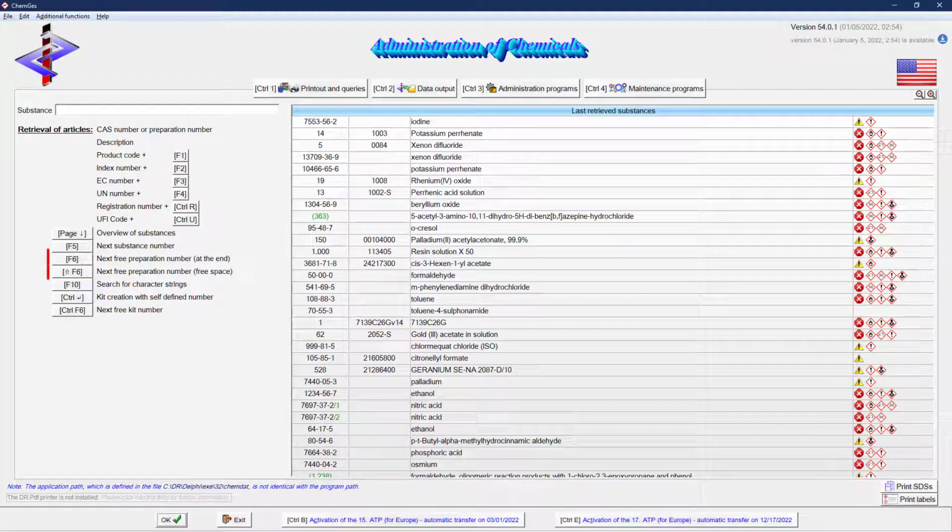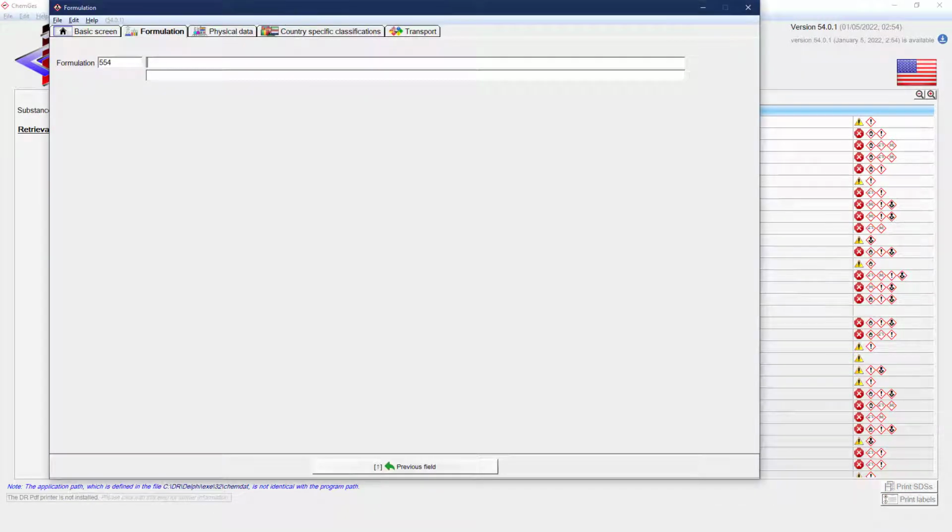Unless you assign the number by yourself, the F6 or Shift F6 keys are used, where the only difference is that F6 increments the highest number already in use by 1, while Shift F6 searches for a free number in the range that has already been used. First, a description has to be entered. Complete the entry by pressing either Enter or Tab.